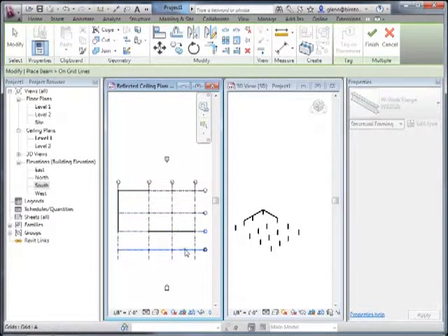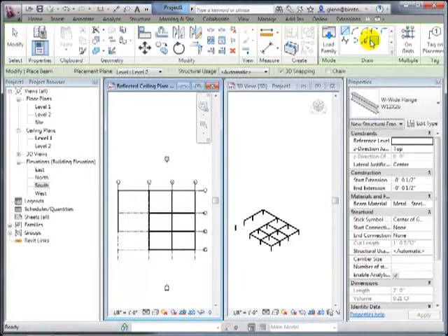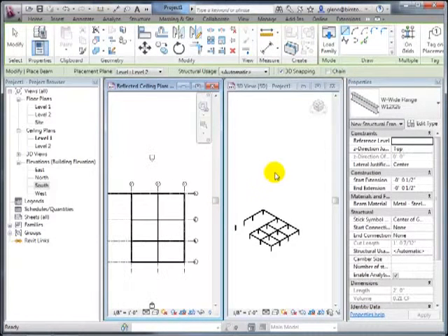I have a question. Yes. Some beams already exist between the two columns. Exactly, a beam on the entire grid. Will it register as there being 2 beams? It'll say there's a duplicate right there. It would warn you. Because they count the materials at the end, right? Exactly. It can calculate costs. So you don't want the double counting. So in this case, if I say finish, it should warn me. It'll warn me at some point.